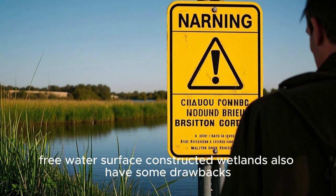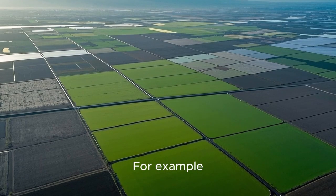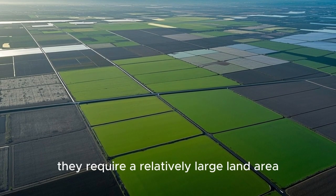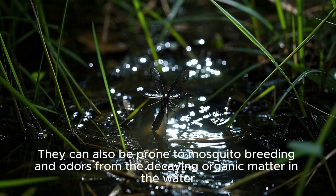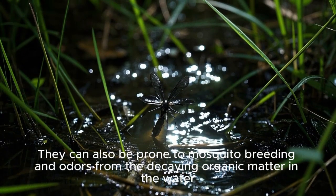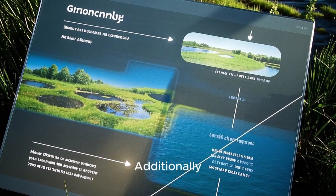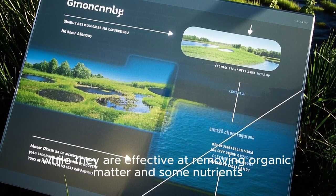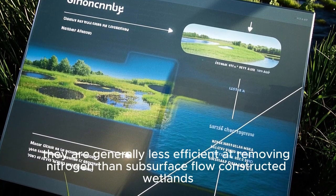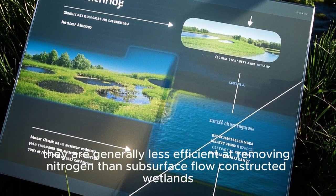However, free water surface constructed wetlands also have some drawbacks. For example, they require a relatively large land area, which may not be available in all locations. They can also be prone to mosquito breeding and odors from the decaying organic matter in the water. Additionally, while they are effective at removing organic matter and some nutrients, they are generally less efficient at removing nitrogen than subsurface flow constructed wetlands.